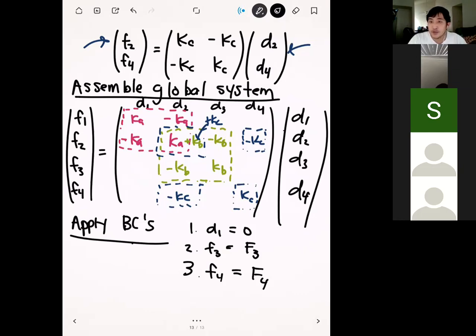All right, Chris, are you still here? You're still here. Okay, so regarding your question from earlier, if you're in 2D or 3D, if you're applying a fixed boundary condition, it's actually the same. So you just follow the same procedure, you just replace the row in the matrix. And so your matrix is going to be a lot bigger in 2D and 3D, but the process is still the same. So if you have a Dirichlet boundary condition, it's basically the same amount of difficulty. It's just you're working with a really, really big matrix.